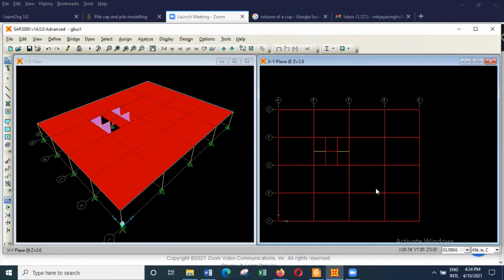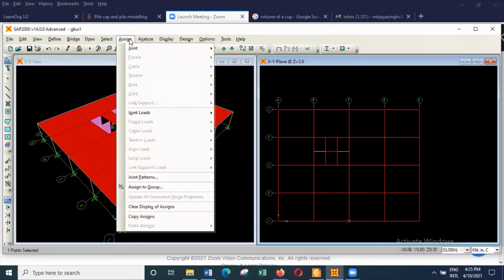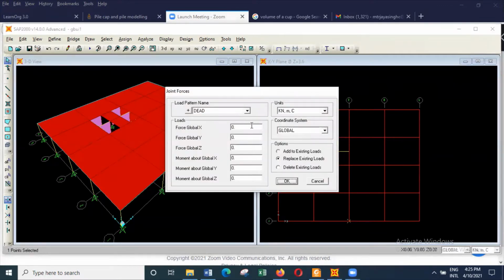And if you want, we can apply the wind load as well. And here I will consider that the wind load does not vary, and actually the wind load varies with the height. But here I will consider that the wind load everywhere in the building is 1 kilonewton per meter squared, which is reasonably representative, but not 100% accurate, but reasonably representative. So what I do is I select here and apply the wind load. Wind in y direction,